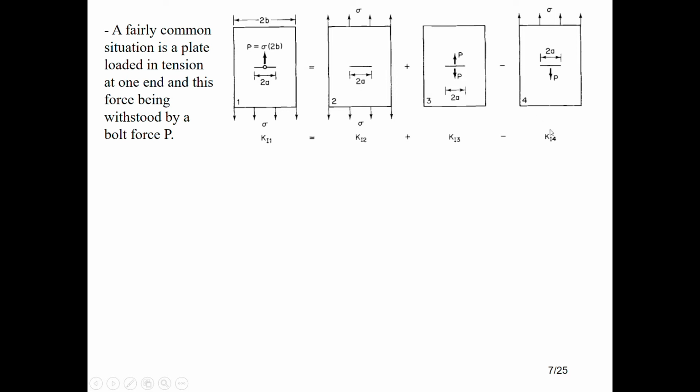Okay, by doing this, to get the whole stress intensity factor, you need to add the stress intensity factor due to this situation plus this situation, and then minus this situation. Only then can you calculate for this situation.